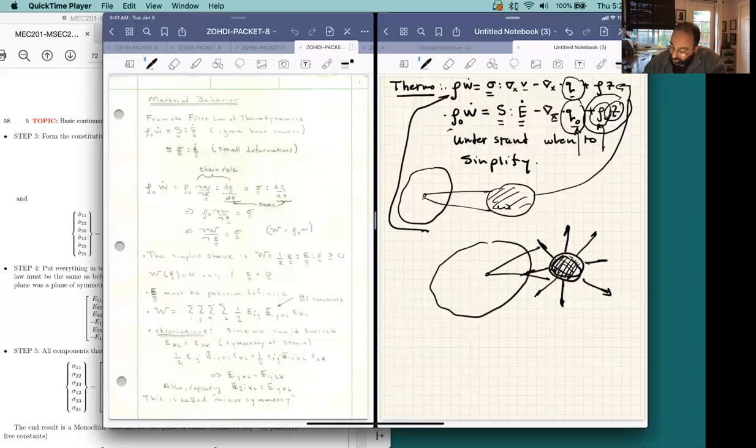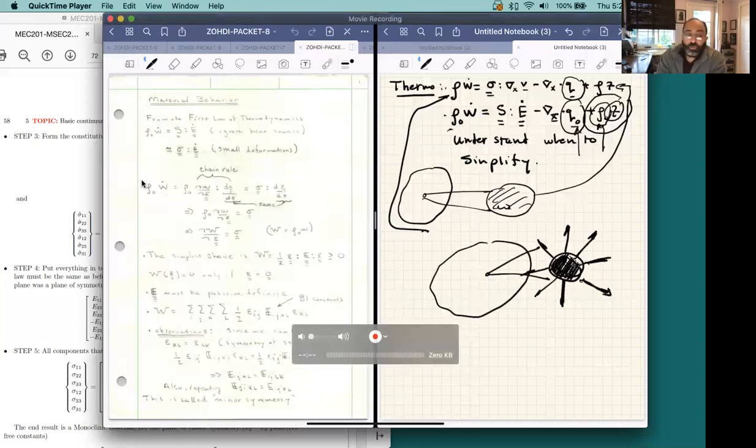And that's simply because the underlying microstructure of the material is amorphous or random or statistically not biased in any way. Therefore, if the material has the same response in all of the different directions, we anoint that material as being isotropic, of course, from the Greek term of iso, meaning everywhere, and tropic, meaning direction. So it simply means that the material has the same response in every single way we pull it.